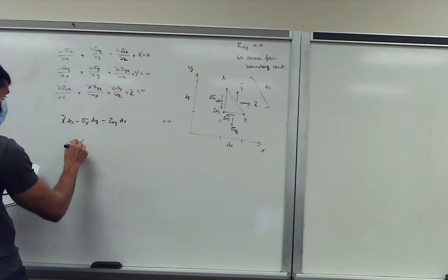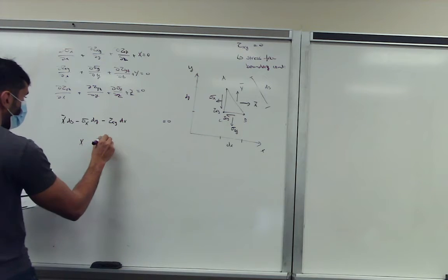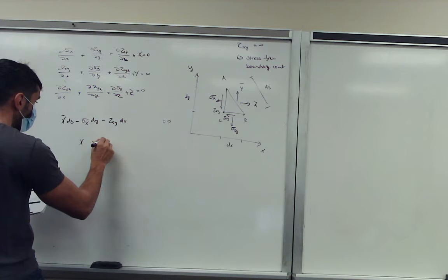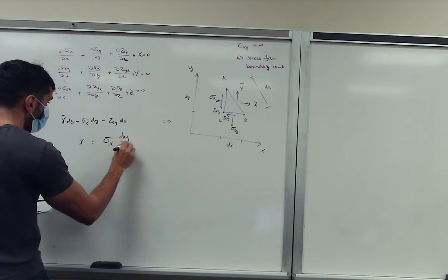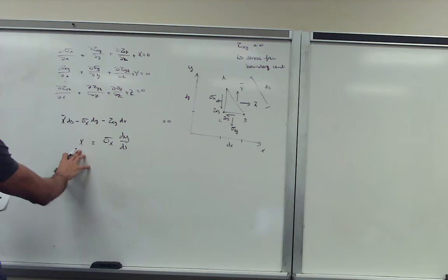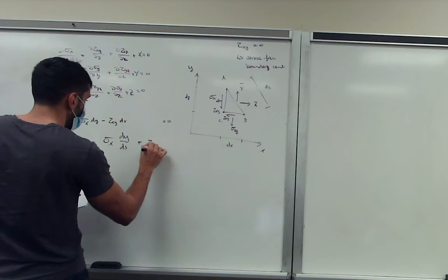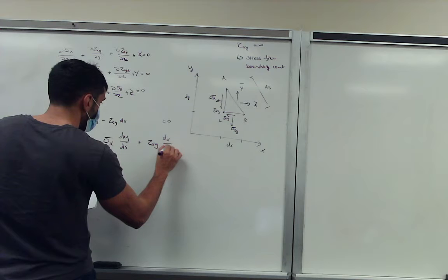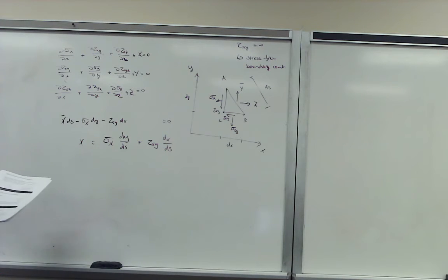Because now we can write this as, I think that was just an error on the lecture slides if I'm correct. We can divide by ds and isolate X, we get tau xy dx over ds. Yeah, I think that half part isn't on the lecture slides. I cannot see exactly where it comes from, so I'm going to assume it's an error. But we'll discuss that next lecture, whether that was an error or came from somewhere else.